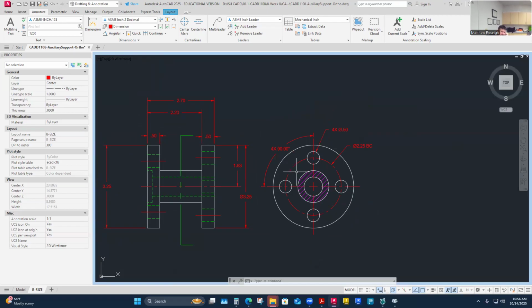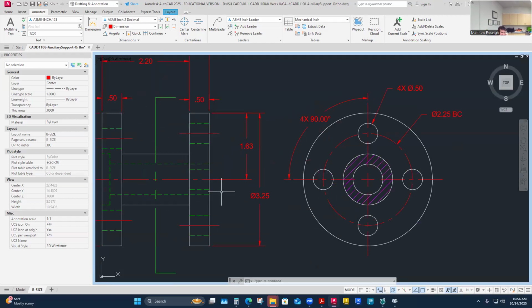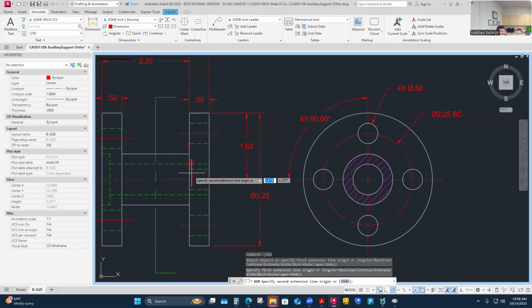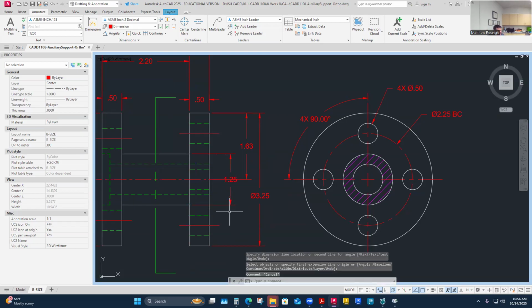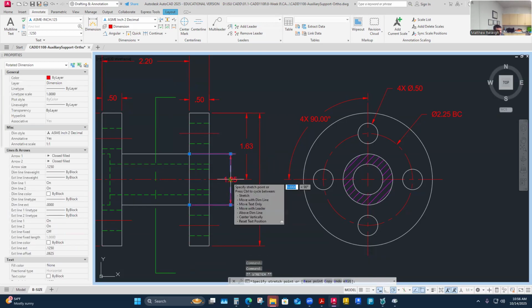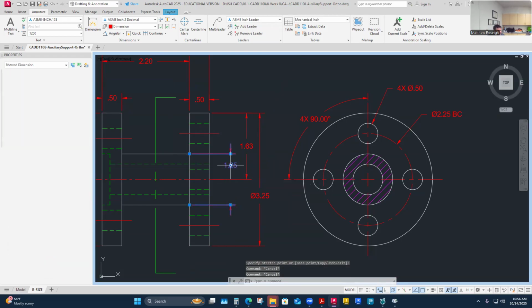Is that all? No, there's these features here that I want to. So this part is actually kind of joined to that part and spans between the two. And this is the clearest place for the inner bore of that part. And obviously I have the outer bore, but maybe it would be better if the outer bore was dimensioned in its rectangular view right here. This is the outer bore. That's a size and that's a diameter.